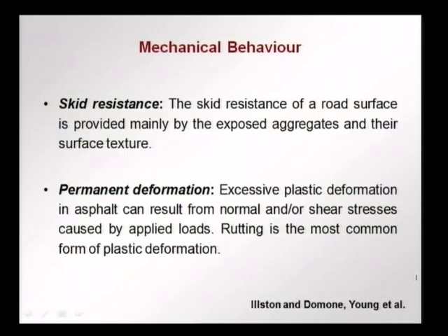So, in order to have this, we need to have some aggregates exposed on the surface. We need to have aggregates that are rough enough. We cannot have something like smooth pebbles over which a car tire can slide. We also cannot have aggregates that break very easily due to the repeated traffic loading. So, we need strong rough aggregates that can be exposed on the surface, and this will give skid resistance and braking resistance.